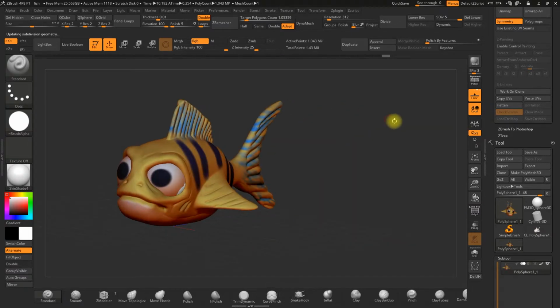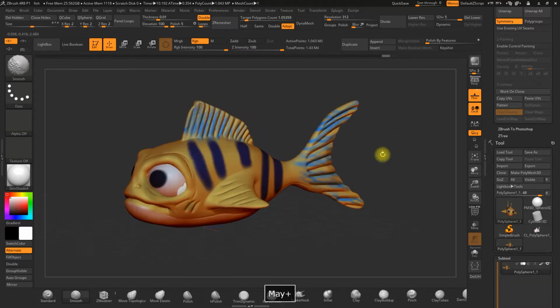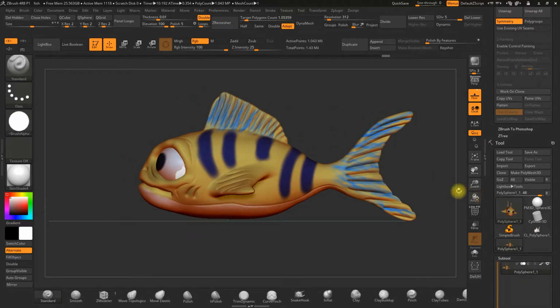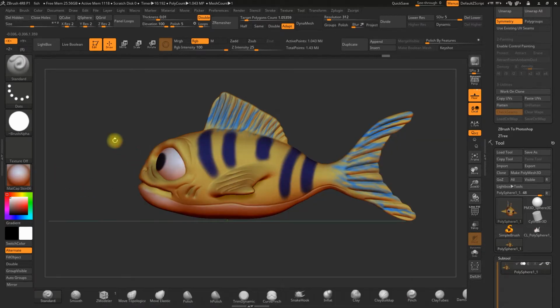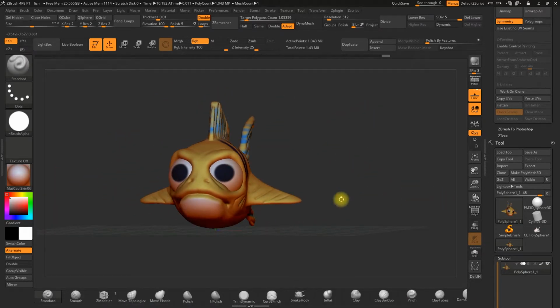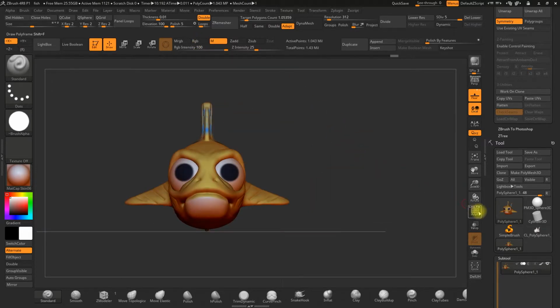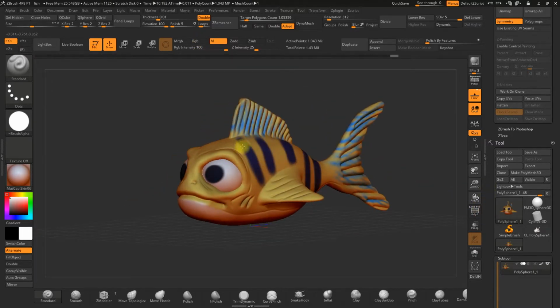So we've taken the UVs from the other model to this one, and we have the UV maps here. Okay, I have a problem with this zone here. There it is. I'm going to switch to Material Channel for a moment and click Fill Object. Okay, done. Now we have the UVs.